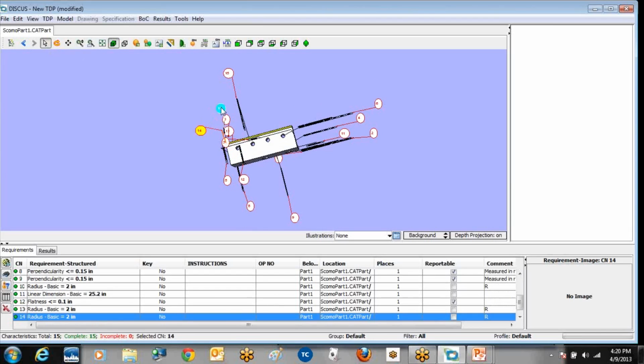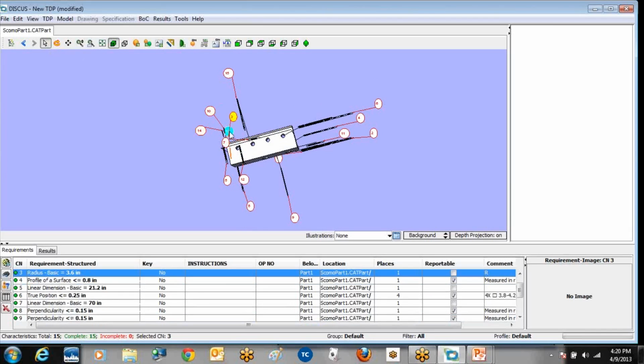Selection tool, let's go back to this. We can move your balloons around. Again, this model already has PMI, product manufacturing information, embedded. We're looking at it solid. Let's look at wireframe. That looks like the skeleton of the model, doesn't it? There's a ballooning tool, a sub-ballooning. We can add markup text, a measurement. We can even cut it in half to see what the cutting plane would be.